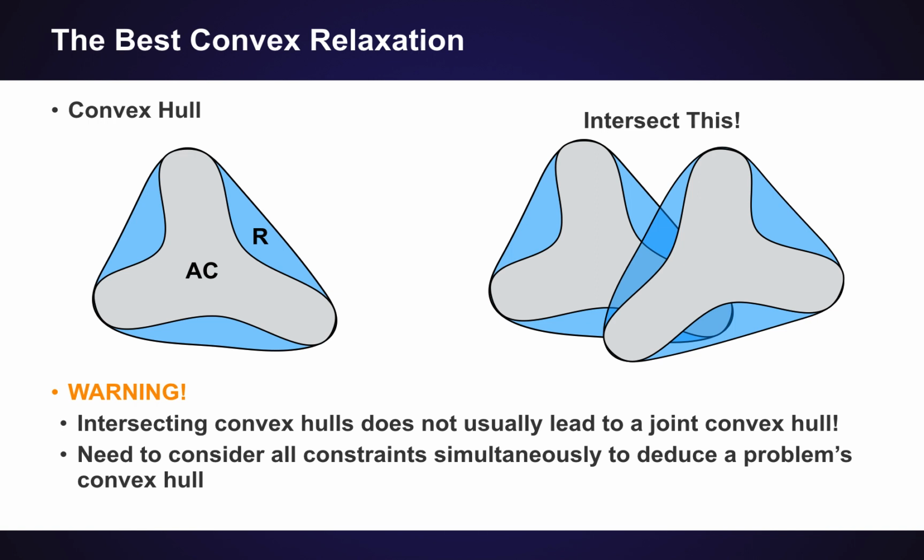Absolutely. And it's worth saying that usually you're trying to prove an analytical form. So I see the data and I just write, this is the convex hull of that data. And that is incredibly challenging for high dimensional information. There are other approaches, say numerical approaches, where you could try to estimate the convex hull by sampling from your feasibility space. So there are other things you can do there, but you just need to be very careful about saying you have a convex hull, because it's quite a significant burden for a big complex optimization problem like AC power flow.